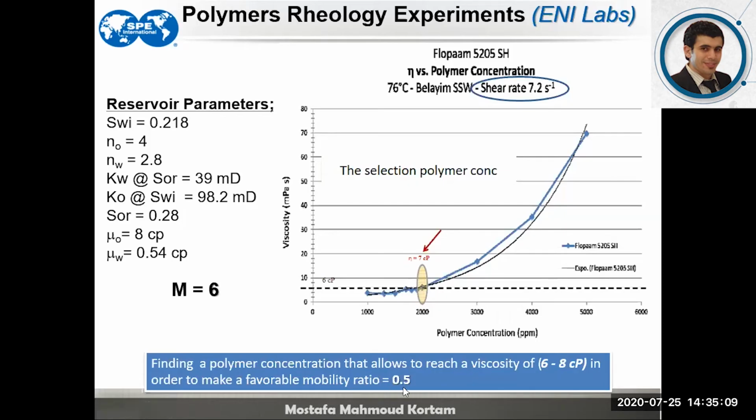Due to the efficiency and the degradation of the polymer, the viscosity may be reduced. So at the end, you obtain a 1. But if you designed your field to operate with a mobility ratio of 1, and for any reason we ignore and don't account for, that mobility ratio may effectively be greater than 1, leading to unsatisfactory results.